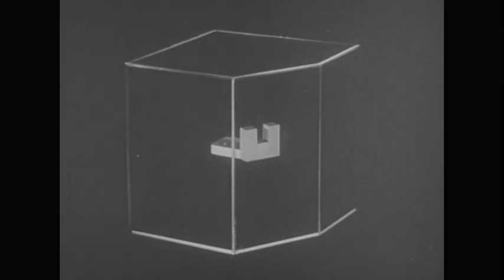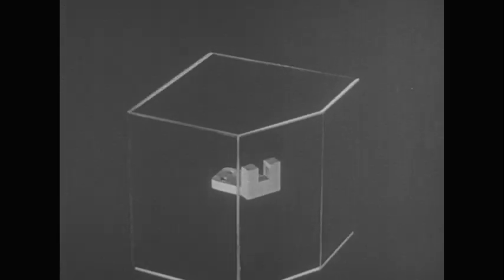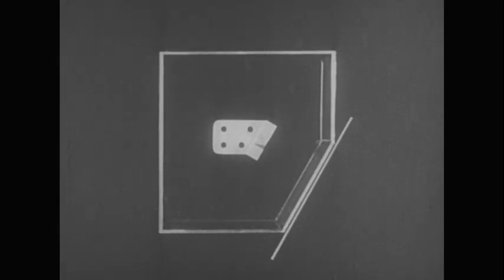In the auxiliary view you have just been studying, the auxiliary plane is perpendicular to the top plane. It shows as a line in the top plane, and this line is parallel to the top view of the slanting face. But the auxiliary plane is inclined to the front plane and to the side plane.